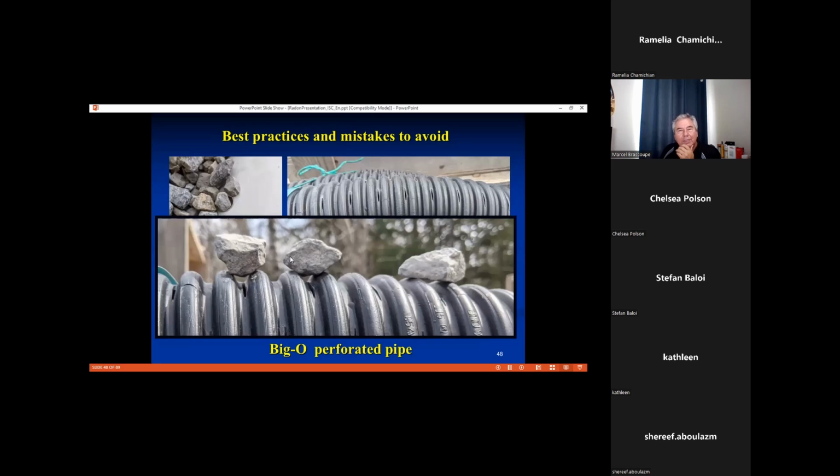If you're using, like we use a lot, the foundation drain with no filter on top, at that point you could see that the crushed stone doesn't come and block those holes. It kind of sits on the mountains, and the holes are all in the valleys. So there's less chance of all those holes being blocked. So we found using the foundation drains to be the better option for us a lot of times.